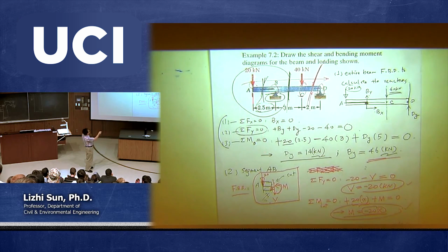So now we have a force going down with a 20. That's why I put 20 here. You cut in here. Obviously, you need to give a shear force by sign convention going down always. It doesn't matter finally if the force is really going down or not. It can be going up. But before we know that, we have to make an assumption. The assumption is on the left, you always assume the force is going down. And in addition, you always assume the bending moment, the internal bending moment, is counterclockwise. And that's our sign convention, which you have in my previous slide.